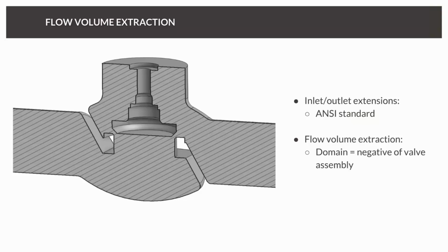So there are standards out there if you don't have an experimental test. But if you only have 2 diameters upstream and there's your pump and 3 diameters downstream, just model that. That's fine. It's better if you're going to try to correlate it. You need to stay close to what the experiment looks like.